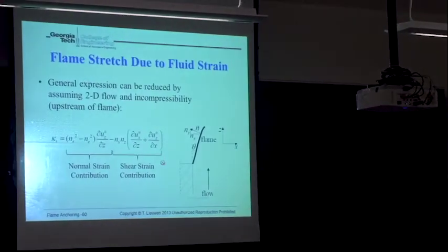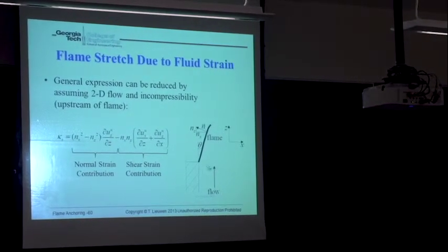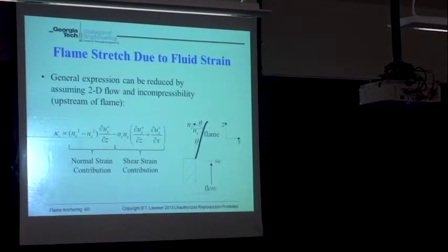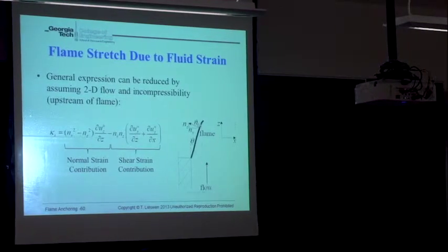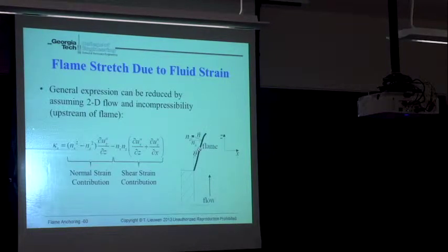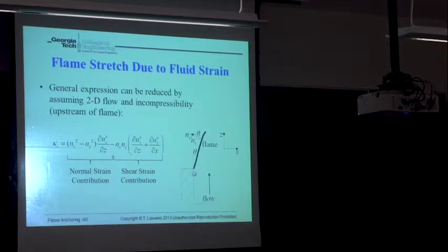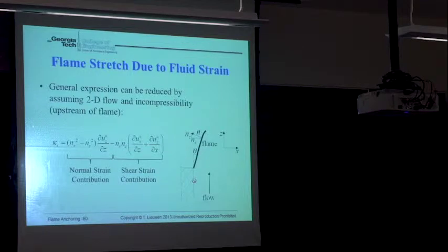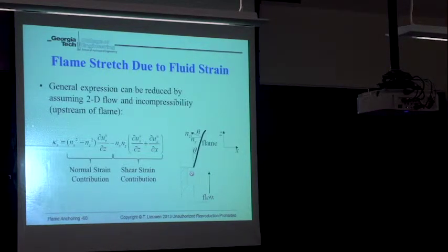So you'll notice this is du x by dz. What we're asking now is, the velocity component in this direction, how much is it changing in the flow direction? And then this term right here, this is the big term, right? This is duz by dx. That's the term because uz is going to go to 0 at the combustor wall in the boundary layer to its free stream value. Duz by dx is presumably going to be very high. So of all the terms here, duz by dx is probably an order of magnitude, maybe even 2 orders of magnitude bigger than every other gradient in the flow, the shear straining velocity term.